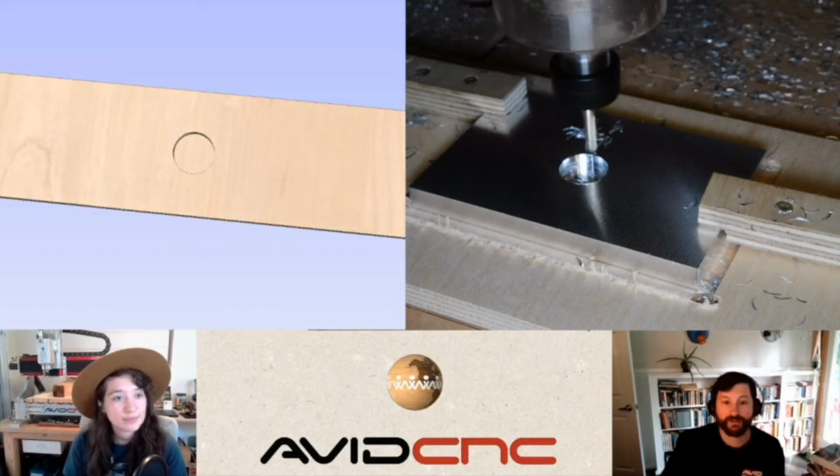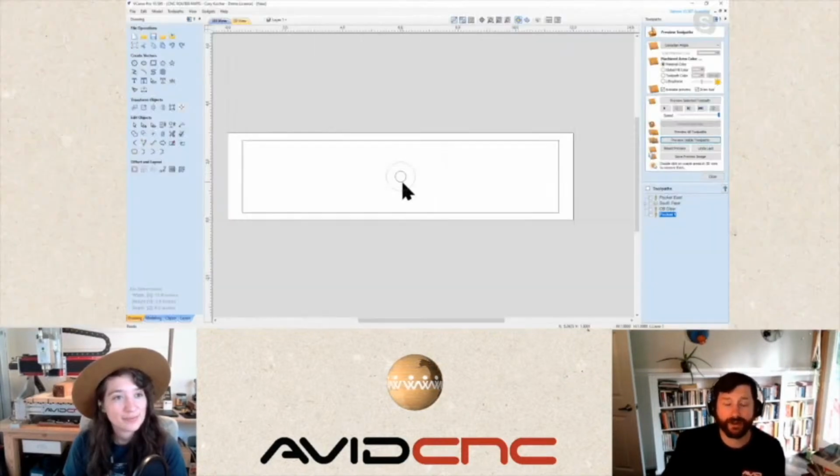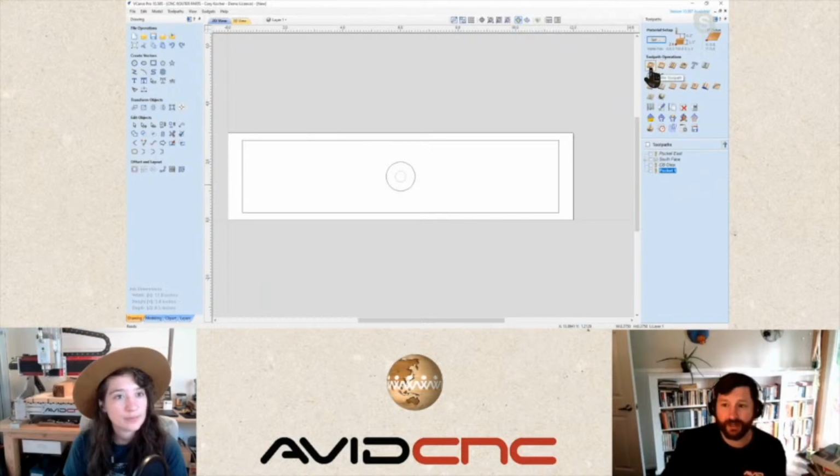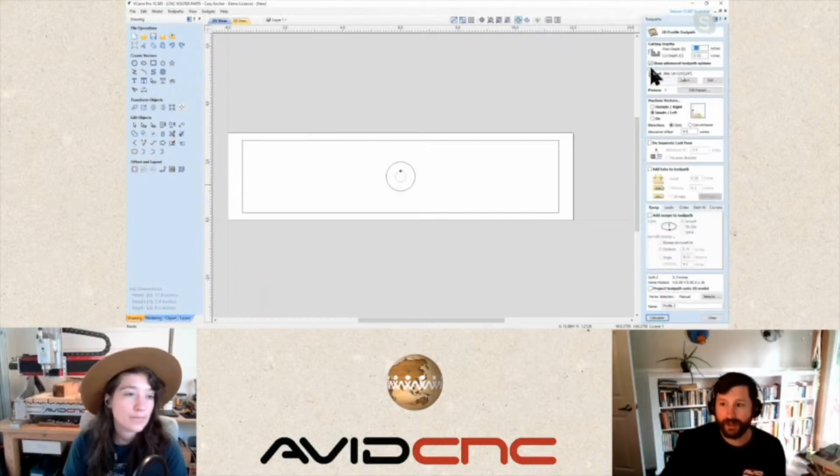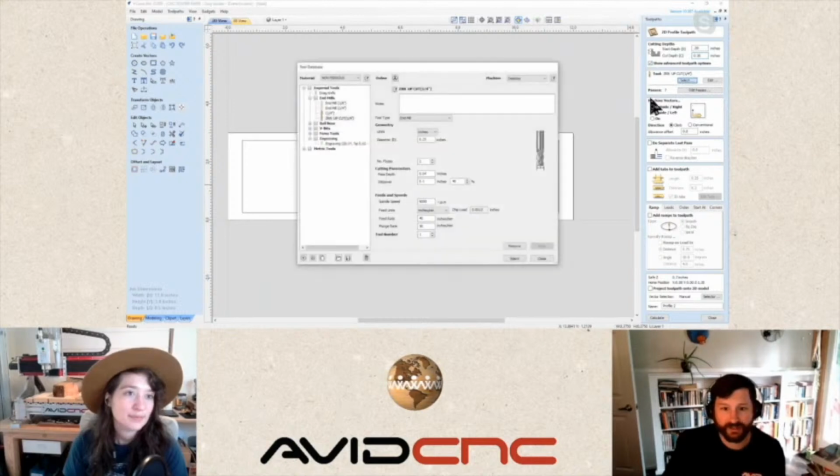Yeah, so let's go ahead and finish off this counterbore now and go all the way down. So I would now do a third toolpath with this inside vector. We're going to do another profile toolpath. We're going to start at a 0.25-inch depth and go to a 0.26, so 10 thousandths deeper than our material. Let's make sure we have the right tool selected here. We have a pass depth of 40 thousandths. Perfect. And we have 9,000 with a 40.